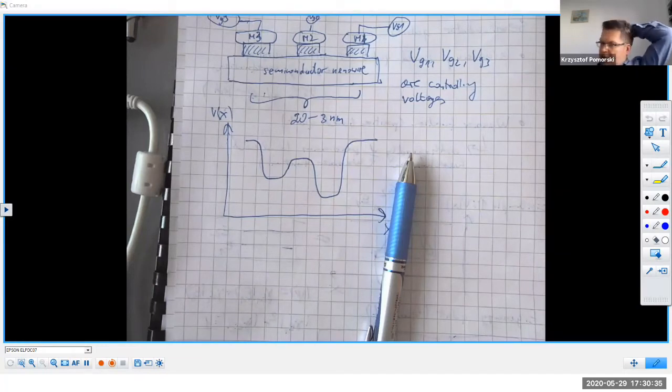The coherence time is in the range of nanoseconds, while in superconductors it can be 500 microseconds, and people are approaching 2 milliseconds right now. So the coherence time is orders of magnitude higher, but at the same time, the scalability of CMOS technologies is incomparable with the scalability of superconducting qubits.